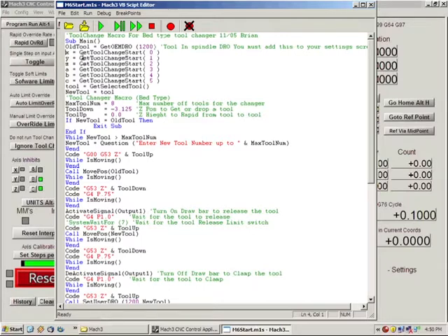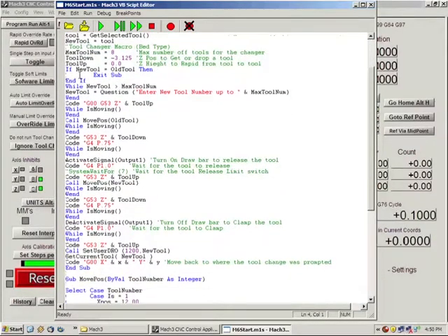We also get our positions where the tool change was initiated, because I'm going to move the machine back to that position when we're all done our tool changes. Here we get our selected tool, which is actually new tool. This new tool could go right up here, but I wasted a little bit of programming and did it that way because I copied that in.